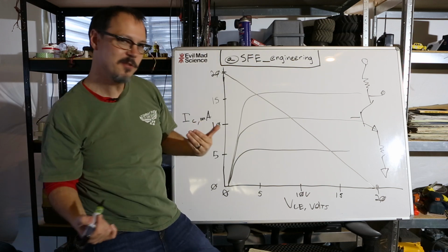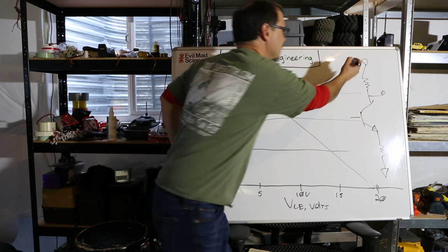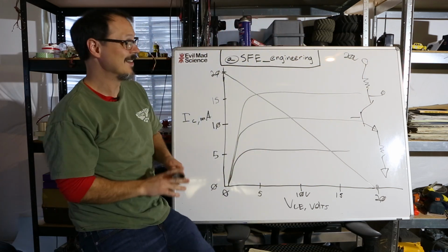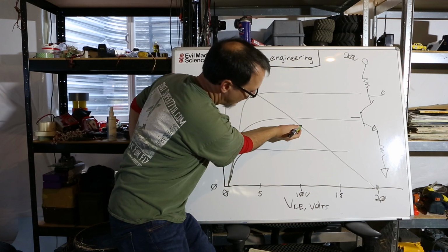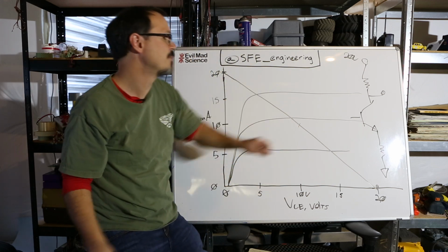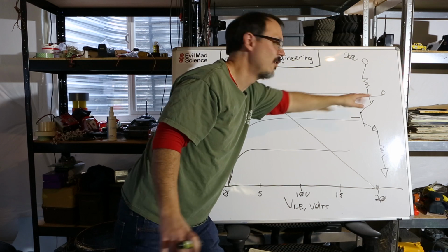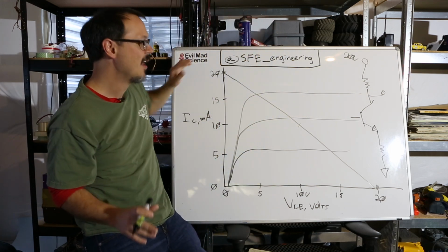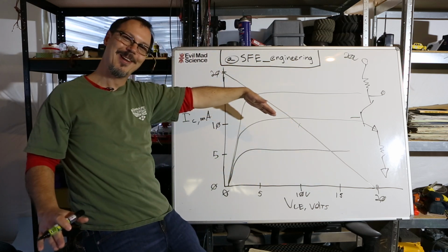It is in our best interest to have that point as near to half of the supply voltage, and if this is 20 volts, half of the supply voltage is 10 volts. That point, 10 volts, I'm going to set there. I'm going to choose this as my operating point. Again, this is where I want the voltage to sit when I've got no signal in. We're setting the circuit DC, and I am trying to describe a load line. I haven't even said the word load line yet.